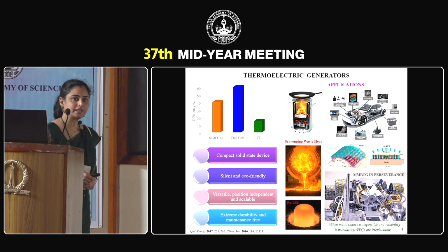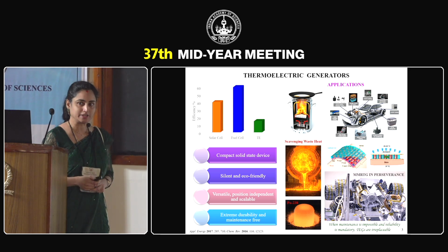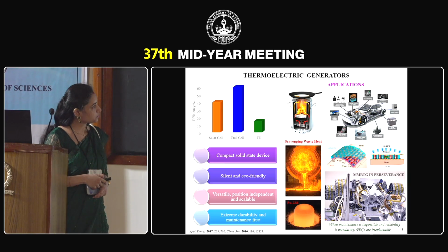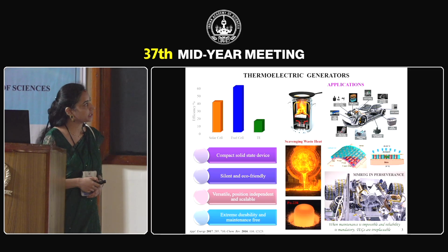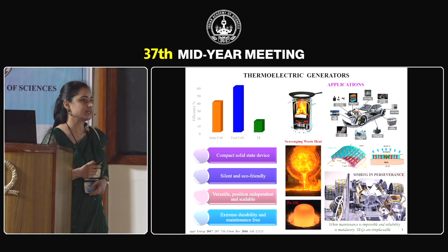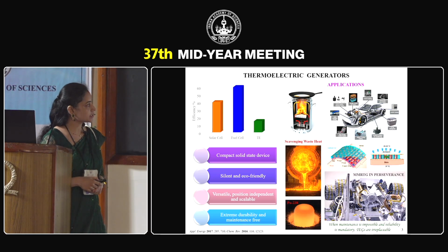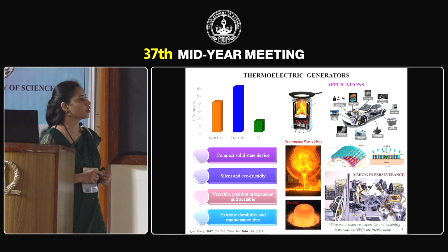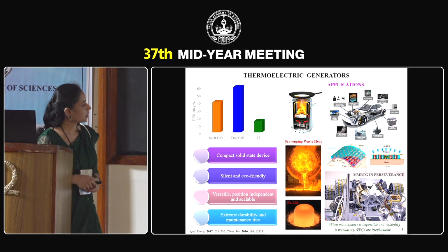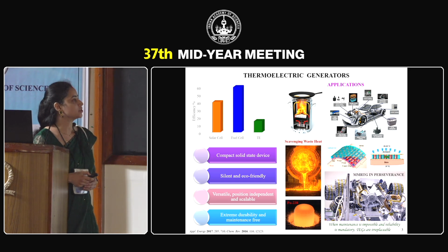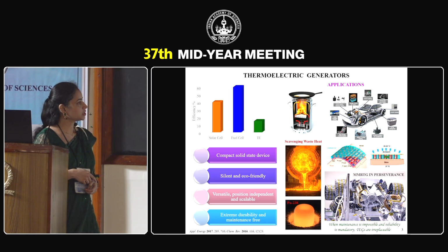So although all the materials have got non-zero thermoelectric effect, in most of the materials it is too small to be useful. And despite low efficiency of thermoelectric materials, they are used in a variety of applications basically because of their reliability. Thermoelectric devices are stable, they are solid state devices, they do not have any moving part, and because of this they can be used in harsh environments for extended periods of time without human intervention because they are maintenance free.